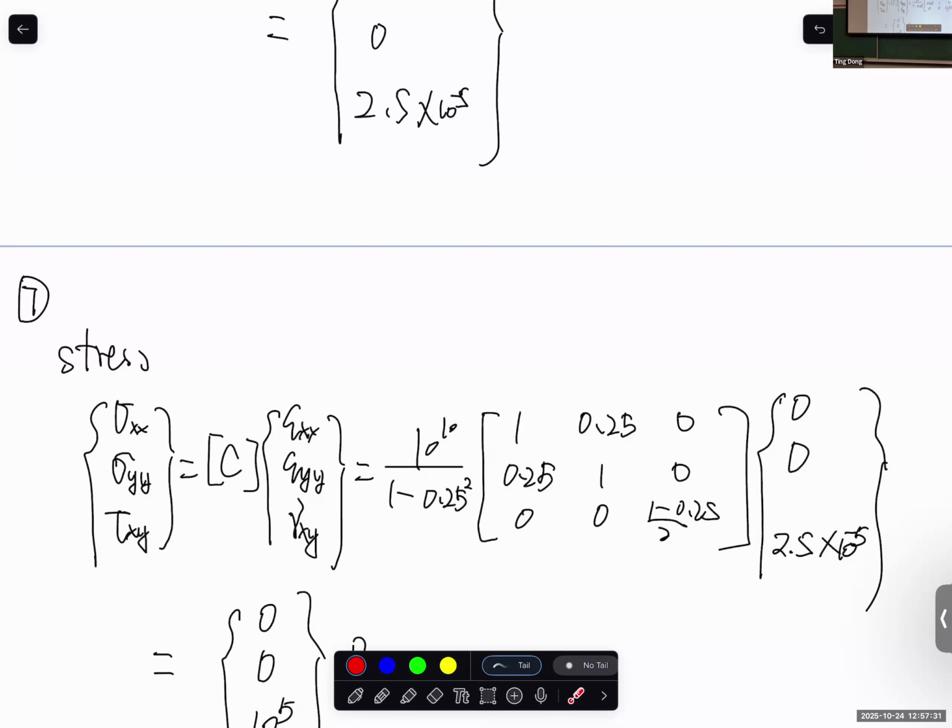So, what you said is correct. Yes, we are using a CST element, and from strain to stress, we use the C matrix. That's correct. But using CST doesn't mean that it's always an approximation, because what if the strain and stress components are supposed to be constant, and we are using an element that has the capability of representing constant stress and strain? Then, from a logical way, there is a possibility that we have the capability to show the accurate results.